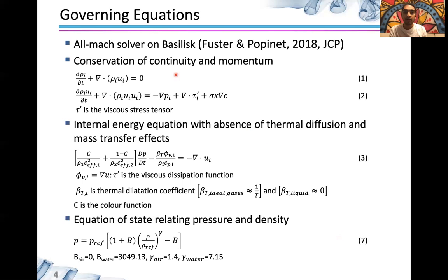Using the all-Mach solver, we are solving the conservation of mass equation. We are also solving conservation of linear momentum, and here is the equation, with the viscous stress tensor. We also take into account the surface tension effect, since we are doing a multi-phase simulation. We also solve the energy equation in the absence of thermal diffusion and any mass transfer effects, so those are not taken into consideration here. And finally, to close the system, we have the equation of state, which relates pressure to density.